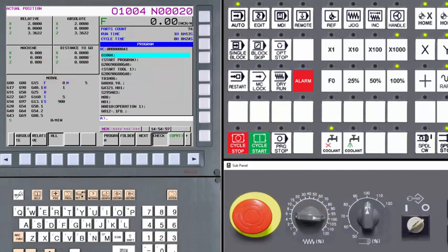Similarly, the spindle speed override overrides the program spindle speed, but it only goes down to 50% for safety reasons. Operators may override the feed rate and/or spindle speed to solve a tooling issue. Some operators use the feed rate override as a kind of accelerator when testing and verifying a program, slowing the feed rate down considerably as it approaches the workpiece, and speeding up when they're sure everything is correct.